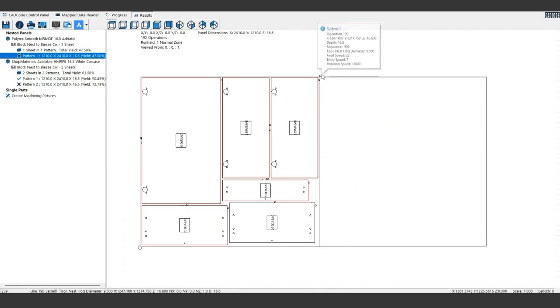We've got a couple of different tools to allow for these offcuts. So what we're looking at is the basic one where we'll just do a single rip to basically salvage as much as possible, but we can also do a full perimeter route of this board, because that will give us the true size, which means we can produce a label, and that label can have the true size and color material listed on there. And seeing as if we do go down that route, we can actually auto add that back into our available inventory, so we can nest against it automatically the next time we use this color. So just lots of tools in there to manage those offcuts as they come through.